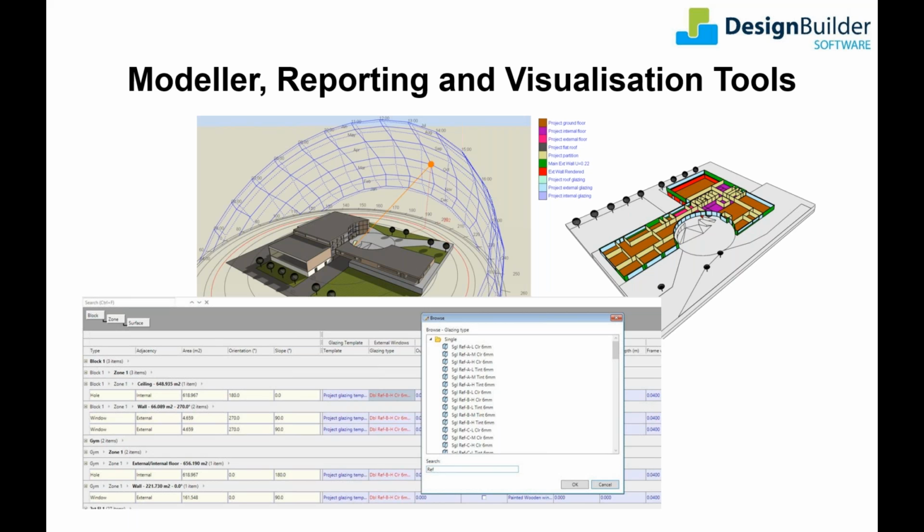The main new modeler functionality released with version 6 is the graphical display of all constructions and glazing used in the model, graphical display of calculated natural ventilation airflows, representation of surface edges in rendered visualisations, site and building rotation, and that's now handled within the modeler, allowing building geometry to be rotated accurately relative to the site.